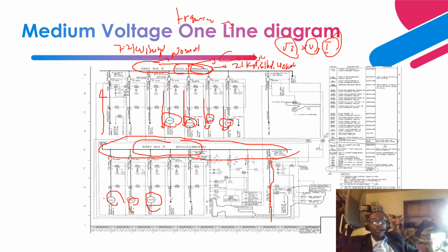being powered. Okay, so on the right-hand side is a legend that shows a naming convention for different types of loads. One of the important things you want to take a look at, if you are learning how to read or draw one-line diagrams, is to look at these legends and their descriptions over here. Very, very important. That's how you learn and build up your capability to draw and understand and read one-line diagrams.